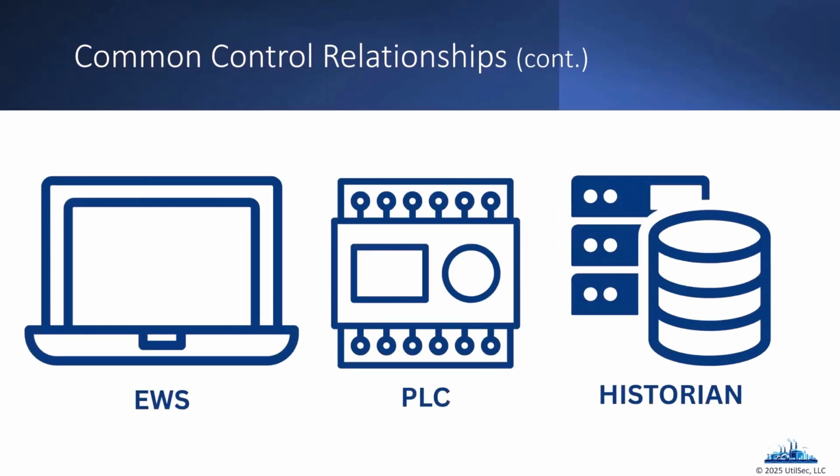Now we might have a PLC, and what if we have a technician that needs to interact with that PLC? Maybe they want to upgrade firmware, or they want to make a change to programming logic. Then they're going to hook up their engineering workstation to the PLC, either directly using a cable like an RS232 cable, or over the network. If we're going to allow them, remember, we're going to put that PLC into remote program mode with the key switch.